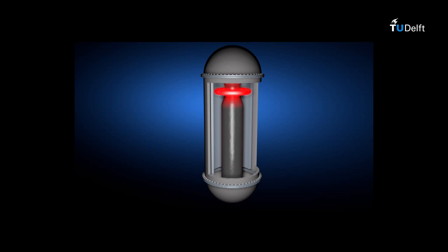The silicon can be doped by adding doping gases like diborane and phosphine to the inert gas to get p-doped and n-doped silicon respectively. The diameter of a float zone ingot is generally not larger than 150 mm, as the size is limited by the surface tension during the growth.